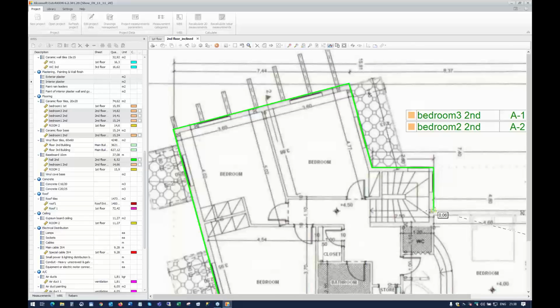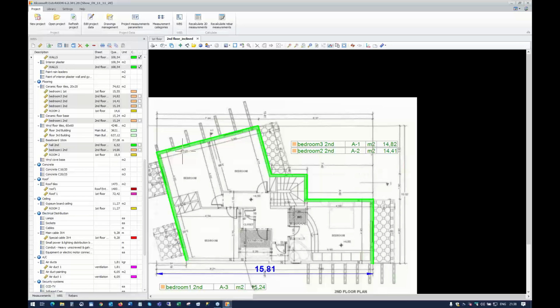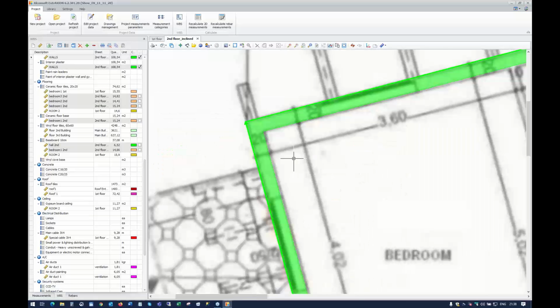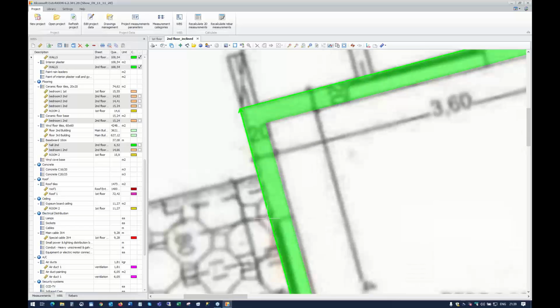Just a minute, because I pan a little bit. I won't measure the whole room, the whole building. It doesn't matter. So an offset line is created automatically. It is transparent, so you can locate the windows, etc. You see this arrow. This means that this line is the main line, the one we draw. So this one is on the left part of the wall.